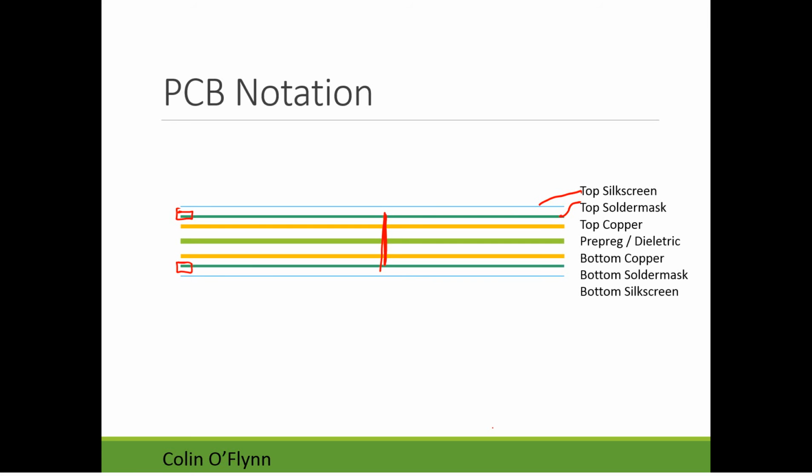The only reason we do that is copper will oxidize, which we don't want if the boards are going to be stored for a while. In between the 2 copper layers, the top and bottom, we have this dielectric layer, or what's known as prepreg often. This is a combination of epoxy and some other material often. It's effectively like a fibrous weave with epoxy stacked in it. It's just some sort of electrically insulating material.